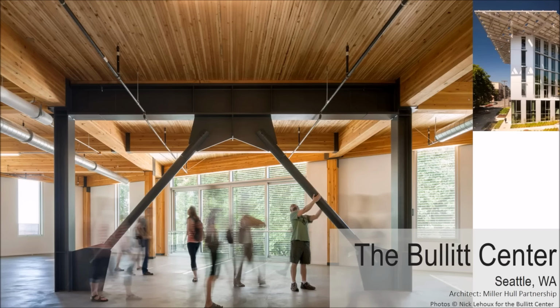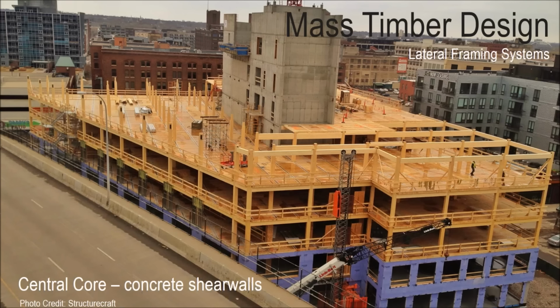So really, as you start looking at and using CLT for floor systems or roof systems or in other components, and you're in a seismic design position, there's not just one solution for a vertical seismic force resisting system. You can really pick from what you have available in the codes today to use with that framing system. The T3 project, which is a six-story, well, it's seven stories total, a six-story wood frame over one-story concrete in Minneapolis, chose to use a concrete core as their horizontal force resisting system in the middle of the building.